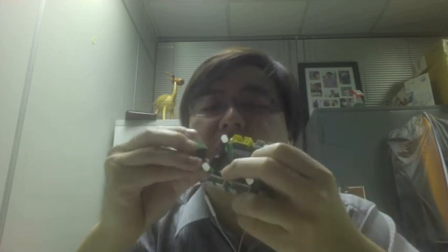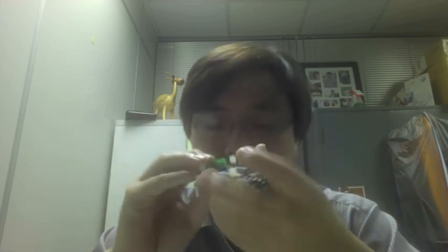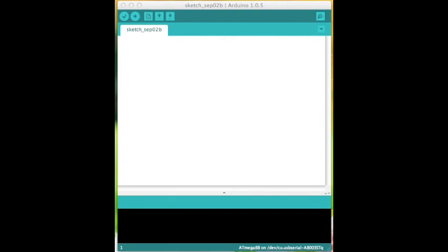In today's lab, you're going to need this 7 segment display, your Arduino board, and the push button switch. Connect the 7 segment to your Arduino board. Connect this one to digital ports number 8 to 13. For exercise number 1, you can just copy the code from the lab sheet into your sketch.